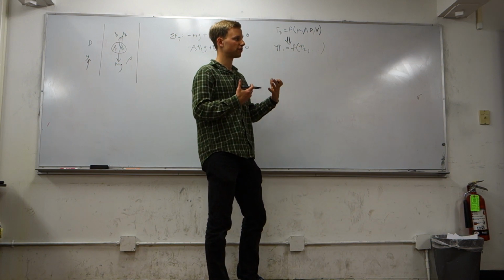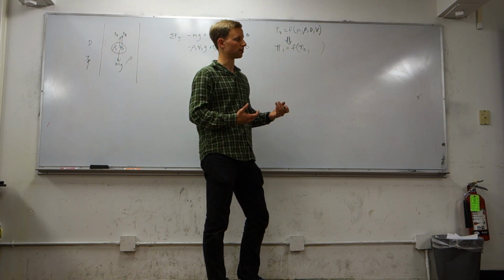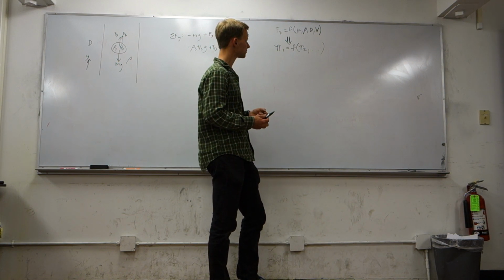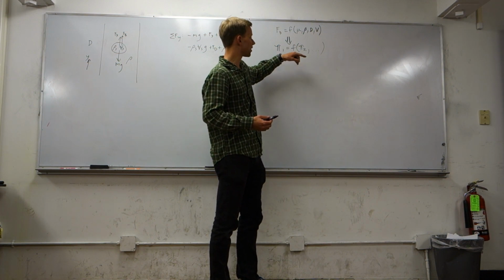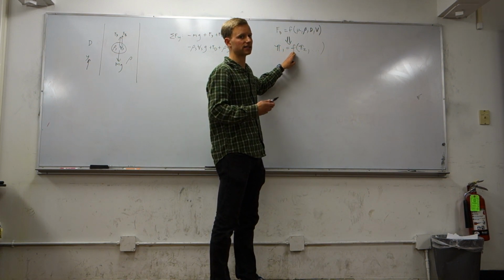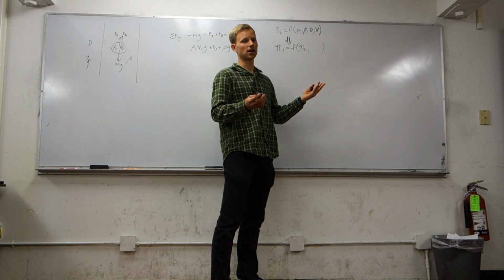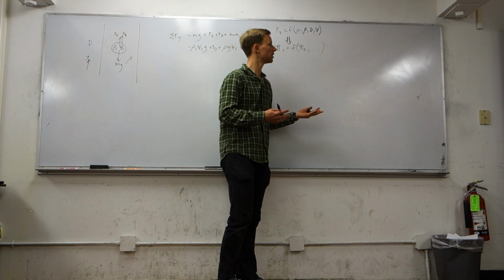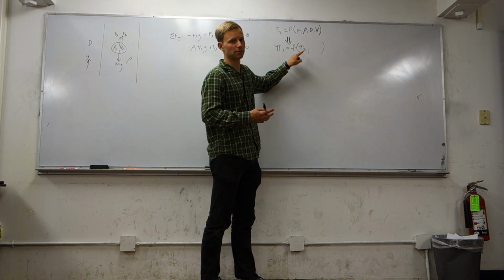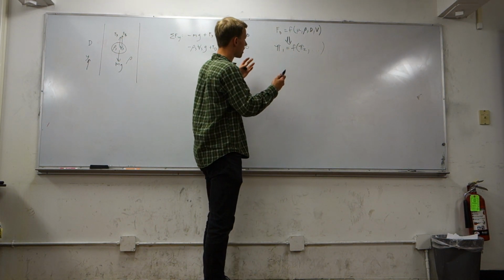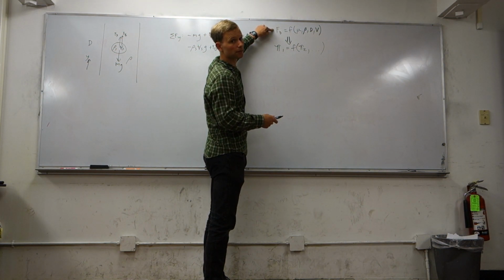That is a universal physical law or rule that you can work with. So in this lab, what we're going to try to do is derive the pi groups, and then we're going to use a relationship that already exists, that someone else has already taken experiments on and already done the derivations for. But we need to derive the pi groups that are relevant to begin with. So what are the pi groups relevant to this problem?